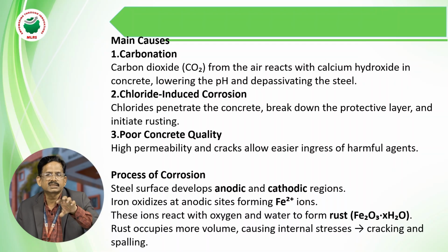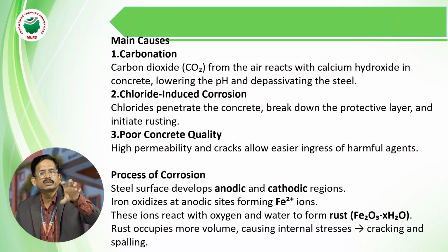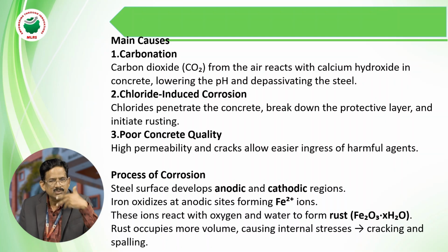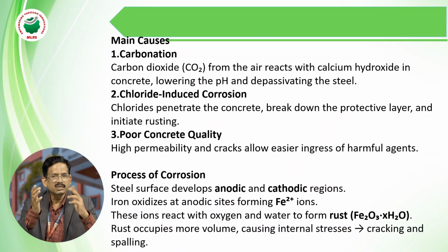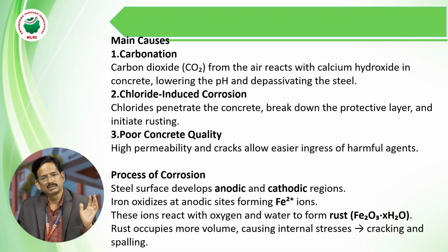But steel is tested in the universal testing machine for Young's modulus. Young's modulus of steel is generally, as you know, 2 into 10 to the power 5 newtons per mm square. Young's modulus is nothing but stress by strain. Stress is equal to load by area. Strain is equal to change in length by original length. Therefore, Young's modulus is equal to stress by strain.